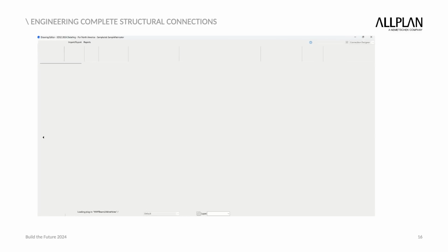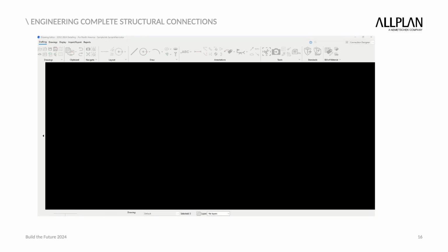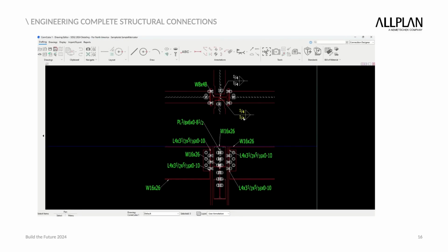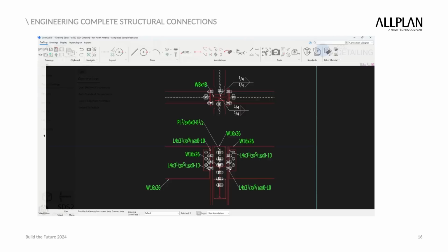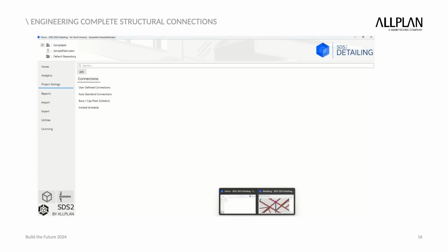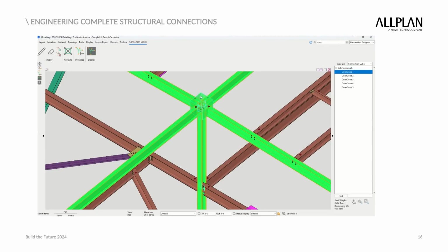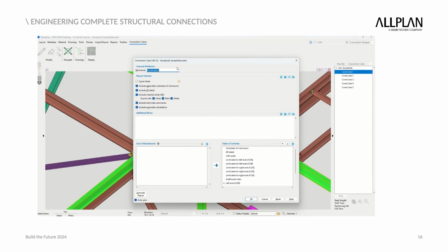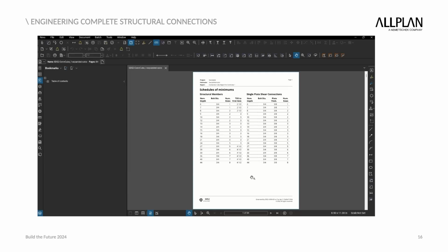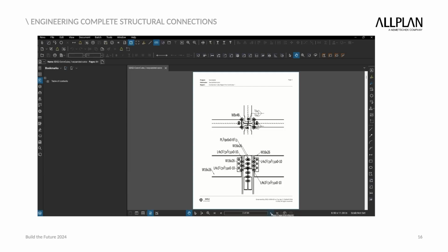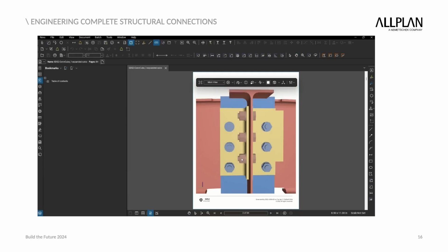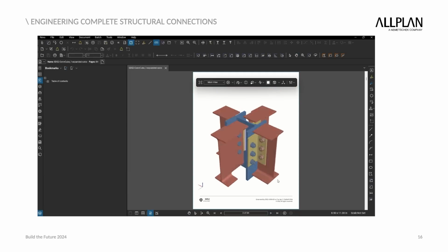Once designed, the 3-dimensional connection cube will detail your connection, giving you automatically generated 2D sketch drawing details of the connections at the node. These drawings can be edited to your office standards within SDS2 and then exported as part of the design package. The connection cube can easily generate a full connection report with complete calculations and detailed drawings in a customizable PDF report.